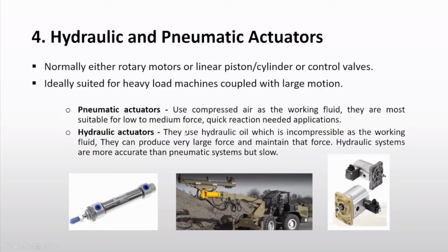In the hydraulic actuators, they normally use hydraulic oil as the working fluid because, not like air, the hydraulic oil is incompressible, so it cannot be compressed. So as it is not compressed, we can use it to work with large, high forces.